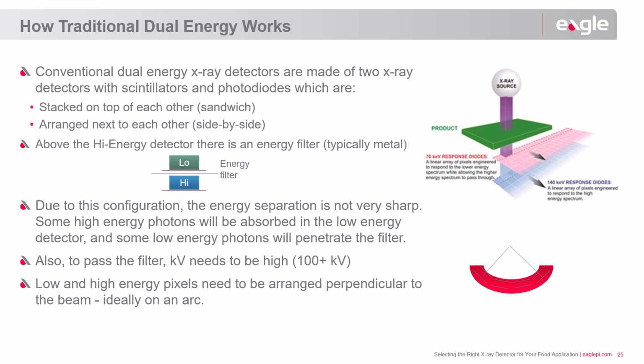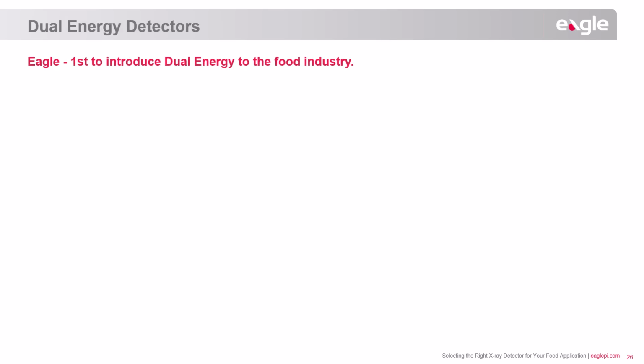Dual-energy detectors represent a significant advancement over traditional line-scan X-ray systems, which operate using a single energy beam. The dual-energy approach employs two different energy spectrums, enabling the system to discriminate between high and low channel X-rays. This differentiation allows for a secondary energy beam to penetrate denser products, thereby improving the detection and visibility of foreign contaminants.